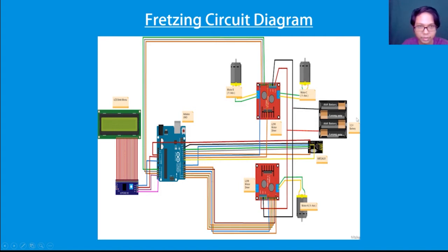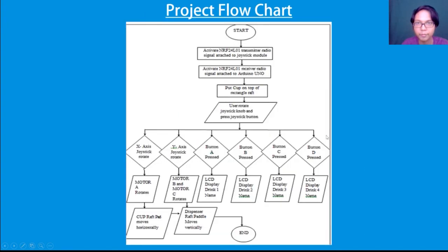And then this motor driver is powered by a 12 volt battery, and then the input is the NRF24L01 for the wireless controller. It's connected to the Arduino Uno.